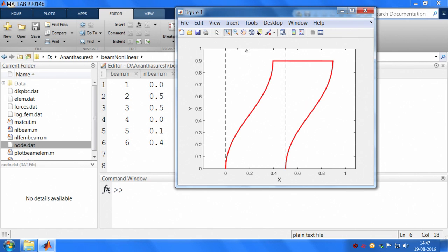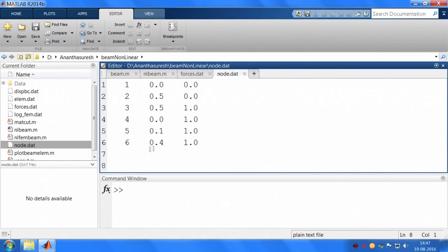So if we do this, just as this is moving down relative to this line, the next stage that we hang is going to move up closer to its relative frame. So this downward motion and this upward motion are both supposed to cancel. So you get this stage to move purely in the x direction. That was the intent of the folded beam suspension. So I am going to add 3 nodes here. So let us put that over here.